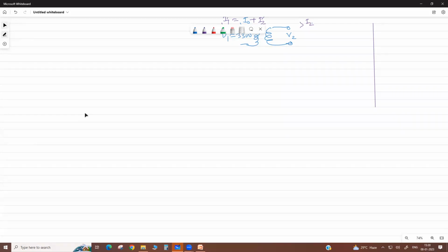Terminal tightness and the protective devices we check. That is maintenance. In an oil type, there is large maintenance, but in a dry type, there is less maintenance. But we remove the dust and check the devices.